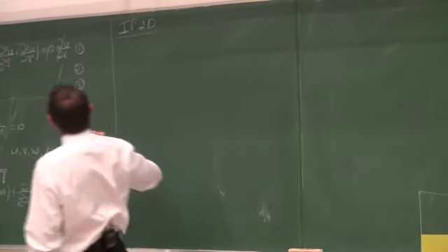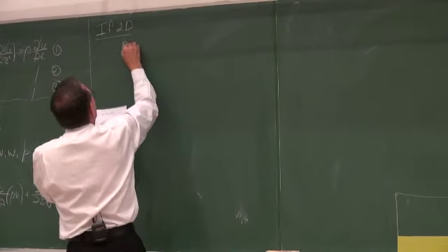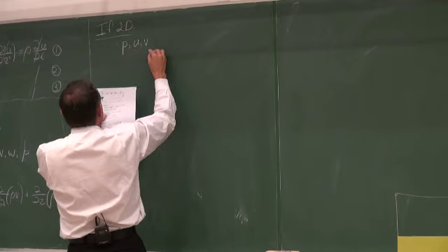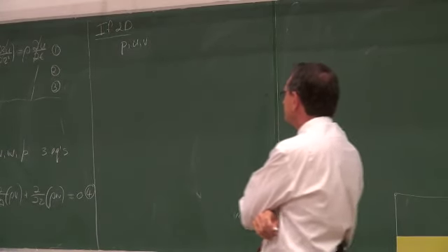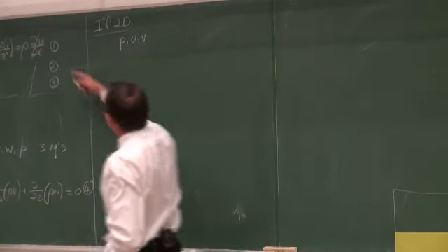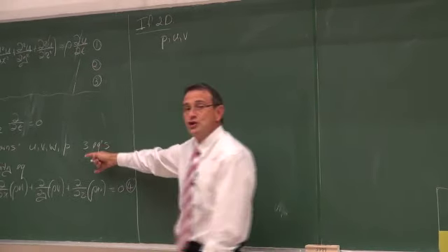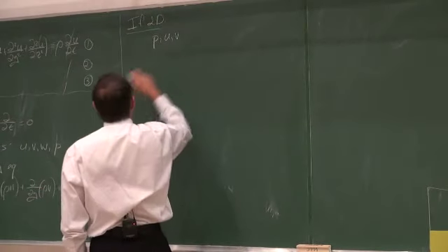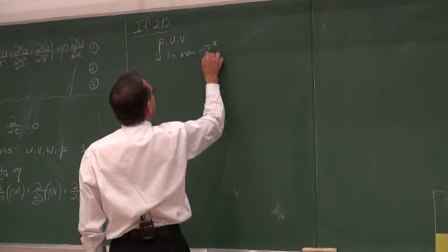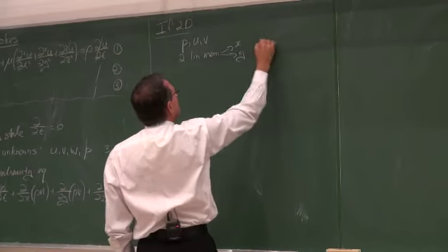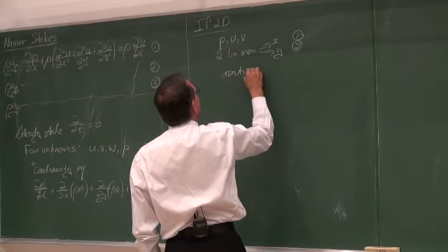Then those terms can disappear, and the unknowns are the pressure and the two velocity components, U and V. But now we have only two momentum equations, the x equation and the y equation, equation 1 and equation 2, and we've got the continuity equation as our third equation.